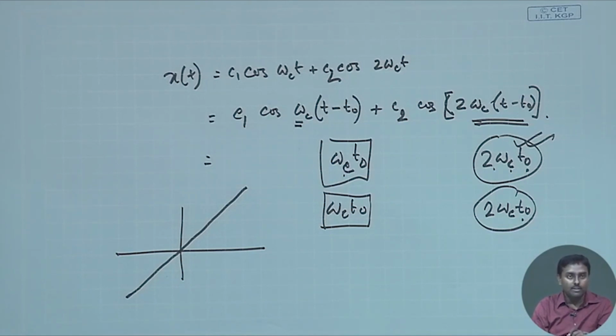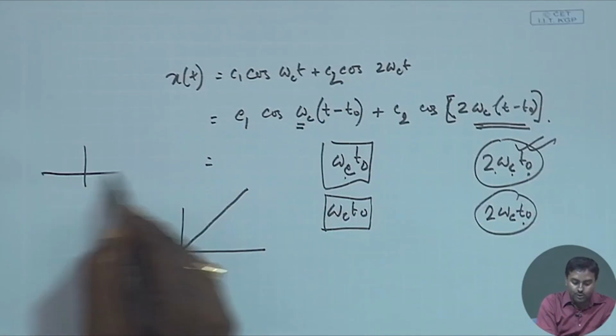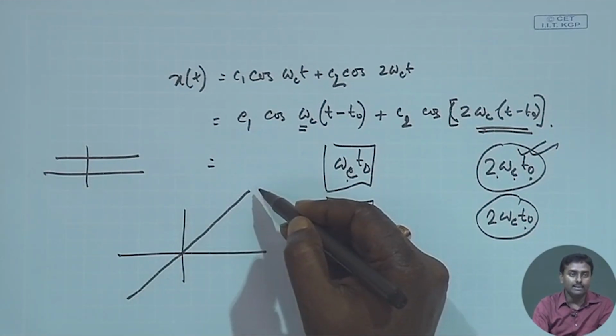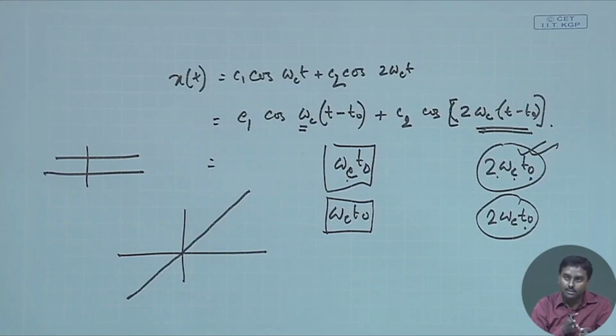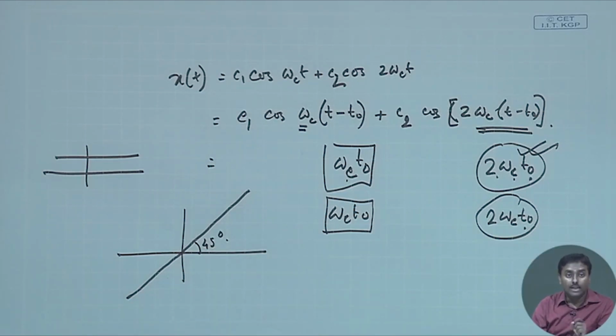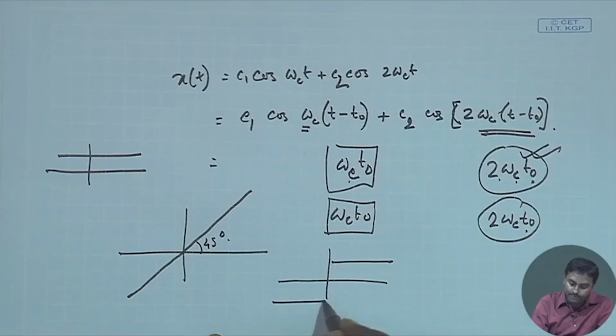Whereas if you plot the Hilbert transform, that will also have the amplitude spectrum as this, mod H(f) will be this, the delay element will be linear. So whatever the frequency is, it will just scale with the frequency term. If the frequency doubles, the phase doubles. So it will be linear with a 45-degree angle. Whereas for the Hilbert transform, you are giving a constant phase shift. Delay will be different. So there the phase shifter is this. So that's the difference between these two.